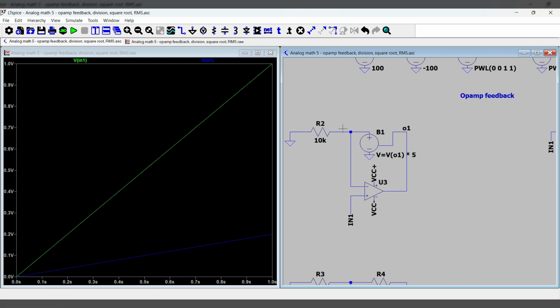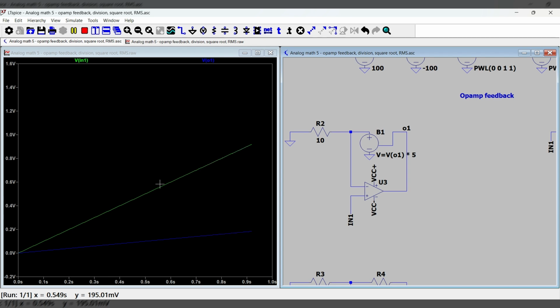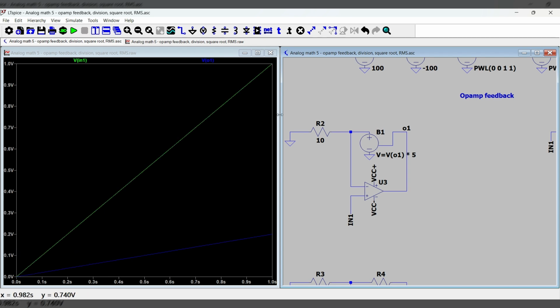Lastly, what is this grounded tap over here? That's essentially just to allow the current to go somewhere, because the current cannot go back into the terminal. There's no current allowed in the terminals. So this resistor is to bleed off whatever voltage is at this point to ground and allow current to flow through it. And it actually does not impact the circuit at all. If we had a perfect voltage to voltage transformation in the feedback, we can change this resistor to like 10 ohms, and you can see it produces absolutely no difference. So here is the same graph again.